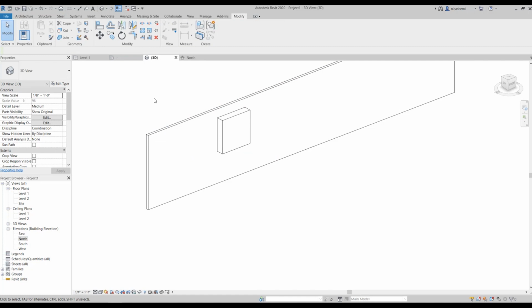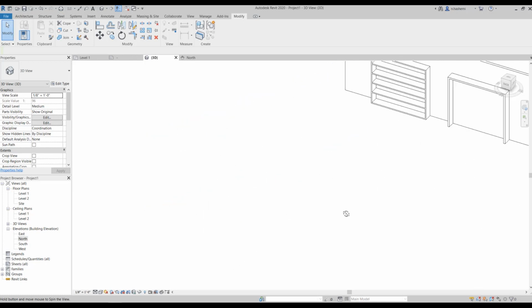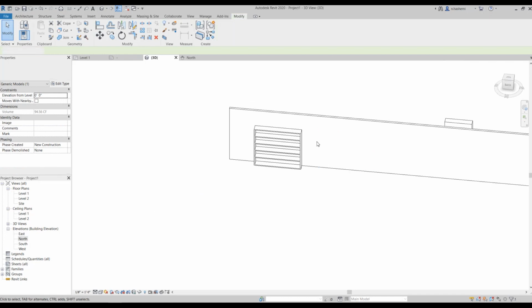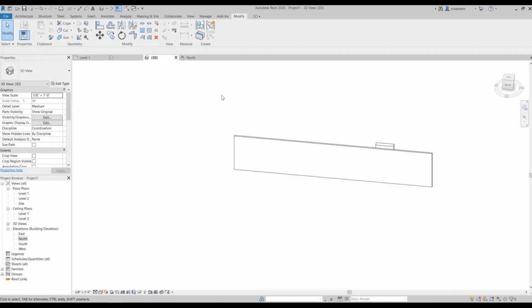This is actually so important because sometimes you may load a model into your project, for example, from a specific manufacturer, like a lighting fixture, and then it is not correct. I mean, it was not created correctly. So, for example, instead of facing down, it's facing to front, and you may need to change it. So you can fix it this way. Now, let's delete these two.